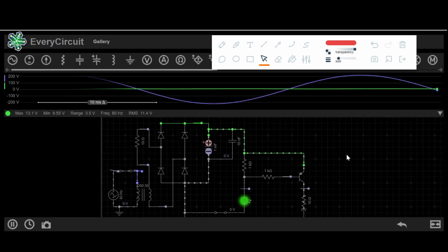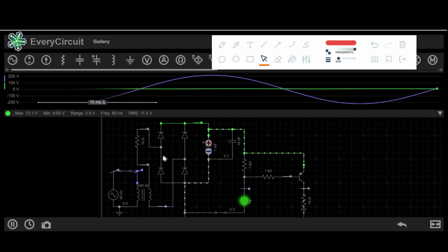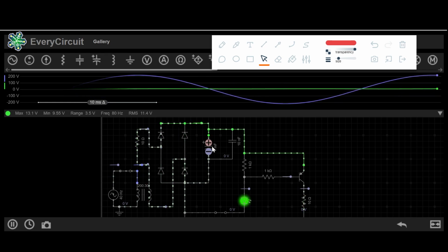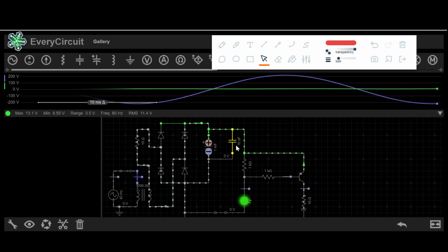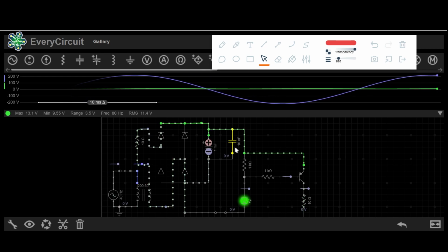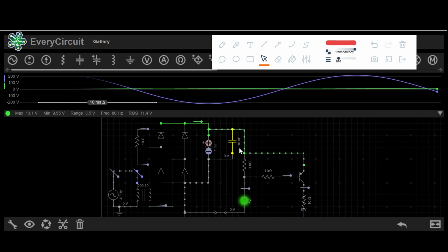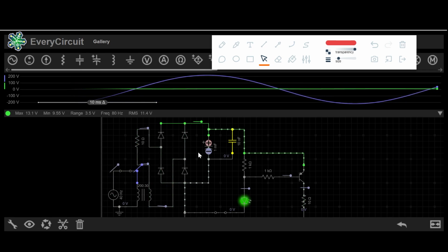So this was about this AC to DC section. And if you see here, you have the low capacitance non-polar capacitor kept parallel to the polar capacitor. It helps to reduce the equivalent series resistance of this large size capacitor.